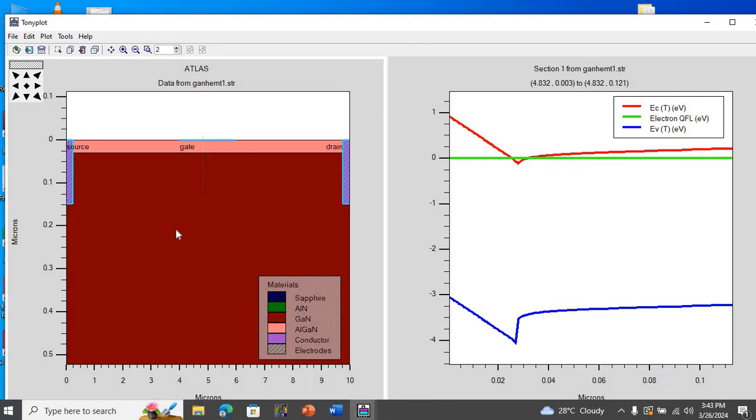Naturally, or we can say inherently, there is still some sort of electron concentration in gallium nitride, but HEMTs are actually based on undoped or extremely low doped materials, and because of that, these electrons are confined to the channel, but they also do not collide with any other impurities, resulting in higher mobility for these electrons.